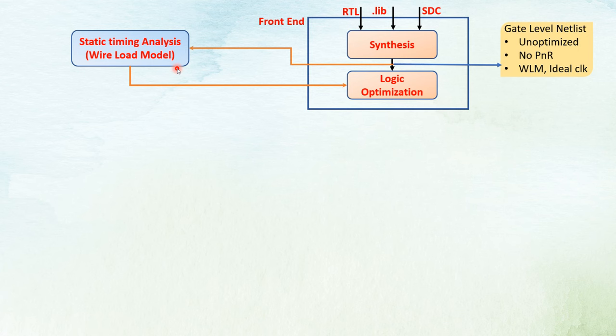So, in layman's language, I'll try to explain this. Wire load model helps the engineer or tool to estimate how long it will take for a signal to travel through a wire in a digital circuit. It does this by looking at the number of pins that are connected to a wire and the length of the wire. When I say number of pins, you can say it basically checks the fan out of the wire that is connecting. This wire load model then uses this information to calculate how much time it will take for a signal to travel from one end of a wire to another.